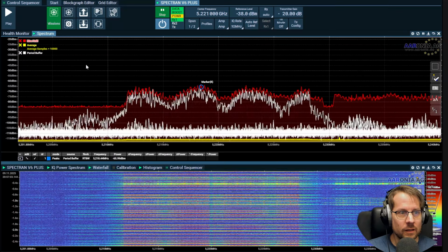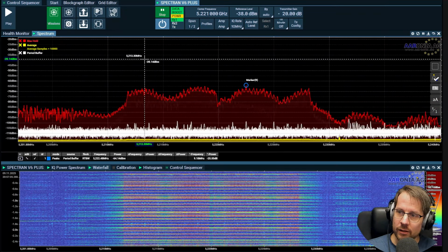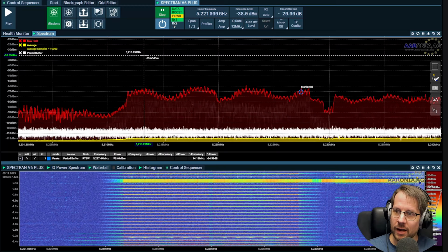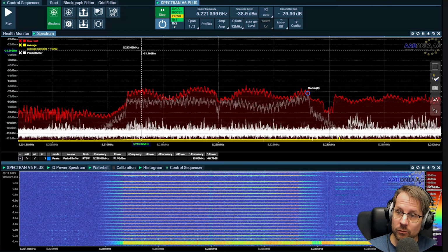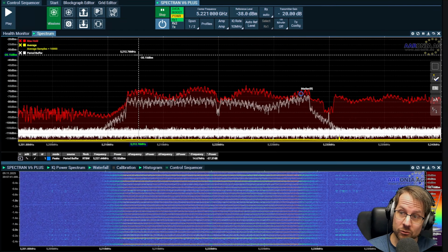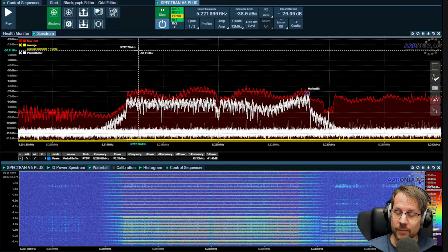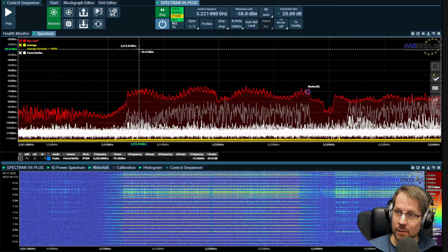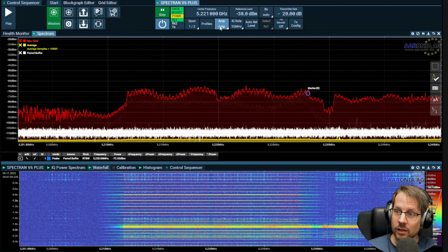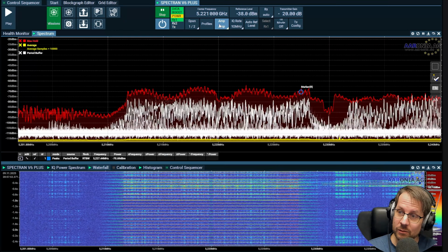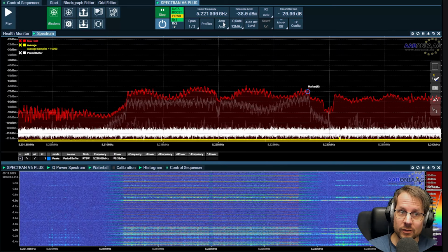And if you've heard the stories that you can burn the amplifier in the HackRF, for example, you can do this with all kinds of amplifiers. If the signal is strong enough, or with static electricity, or something that severely overloads an amplifier, it will break. When that happens, it will act as an attenuator.